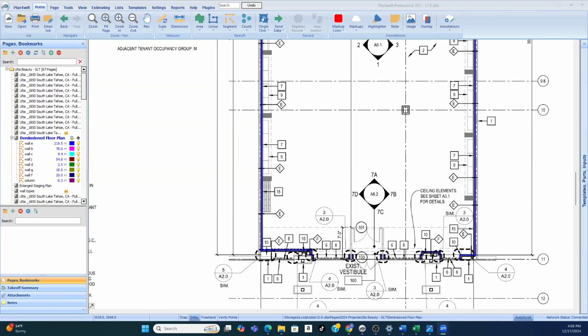Number 2 is breaking down all of the floor plans. So we have a floor plan, we have the roof plan, we have the reflective ceiling plan, and going over all of those plans and identifying the symbols for each of them. And also, we may barely just get through this module number 2 tonight. And going over all the symbols for all of the plans and how to apply plan view, section view, detail view, elevation view to each of those plans, and how to make sense of all of that. And of course, looking at the dimensions and the scales and everything.